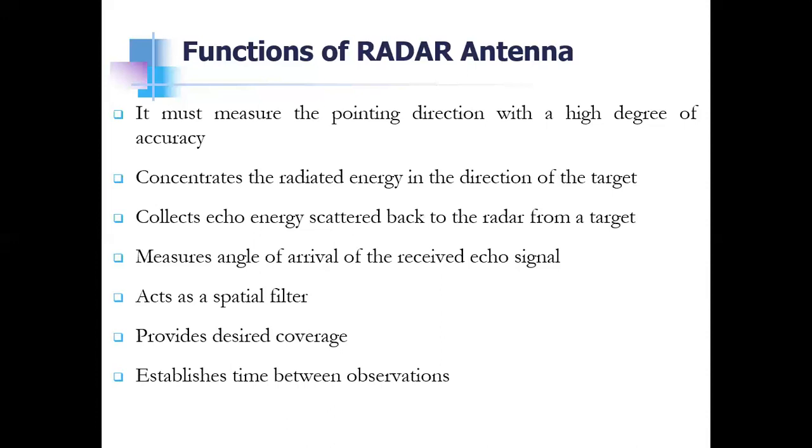So you can steer the beam as per the directions of the desired targets. Directive antennas mean you have narrow beam widths, and that results in accurate angular measurements. That means it will exactly point the direction of the target. Okay. Another important advantage is that we usually operate these radar antennas in microwave frequencies.